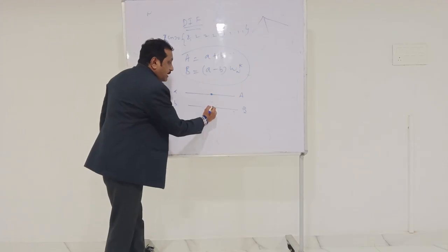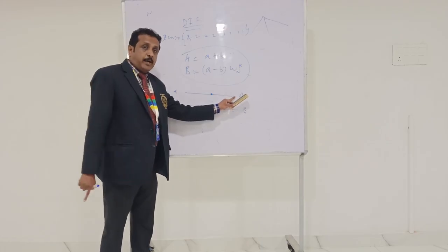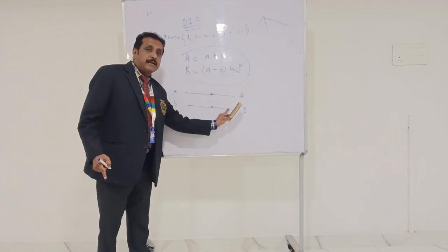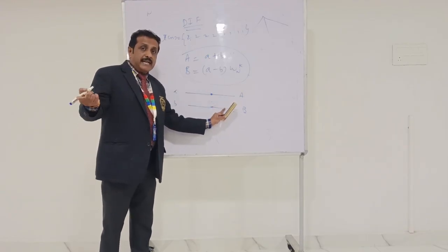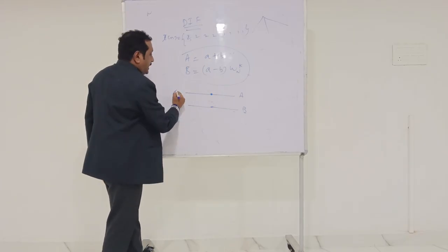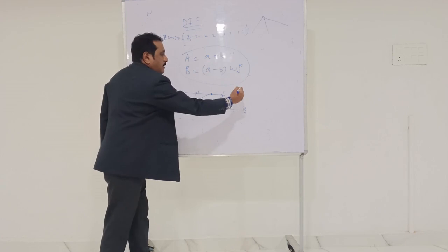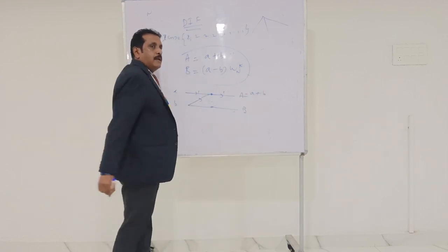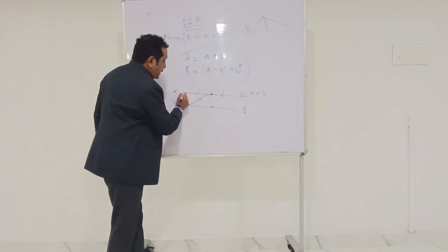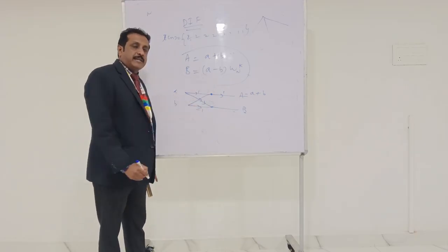Now here the adder is in the middle. In DIT, the final end point is the adder, where addition is carried out. Here, at the middle, the addition will be carried out, and after the addition, the multiplication will be carried out. That is the major difference between DIT and DIF. Now, first, if you want to get capital A, you have to add A with B. So both will be added together, and finally you get A plus B. If you want to get capital B, one of the inputs is A, from here, and another one is minus B, so the multiplication factor is minus 1 here.